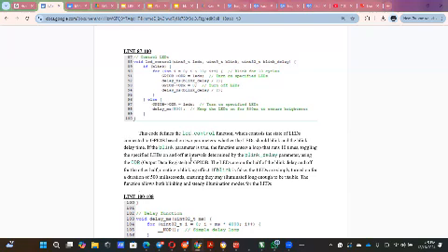If the blink parameter is true, the function enters a loop that runs 10 times, toggling the specified LEDs on and off at intervals determined by the blink delay parameter. Using the ODR, output data register of GPIOB, the LEDs are on for half of the blink delay and off for the other half,